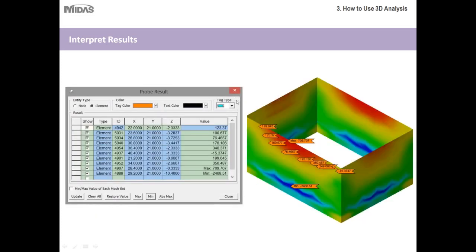Okay, and then for those of you who want to import your results to a spreadsheet, with Midas GTS, this is a very specific example to GTS, but I'm sure Plaxis and GeoStudio have their own ways of doing it as well. So if, for example, I have my retaining wall, but I want a spreadsheet that I can give to a client for some more clarity, I can tag certain ranges or certain sections, and then I can export those results into a spreadsheet.